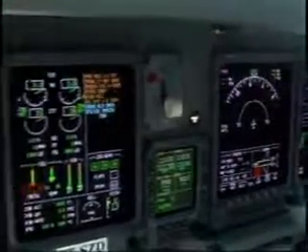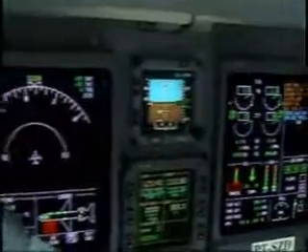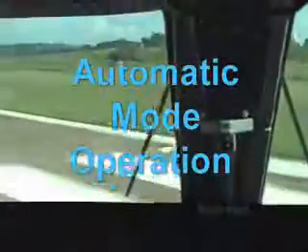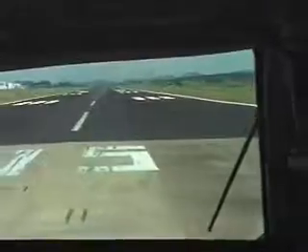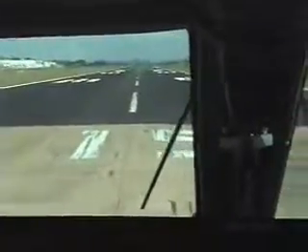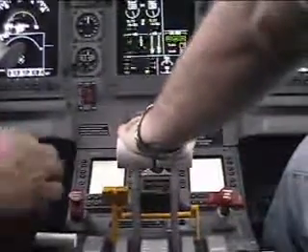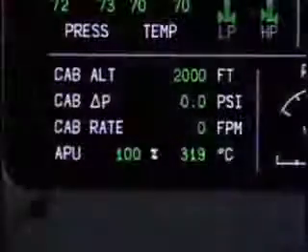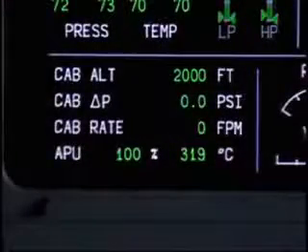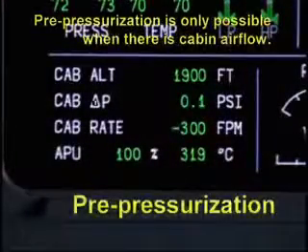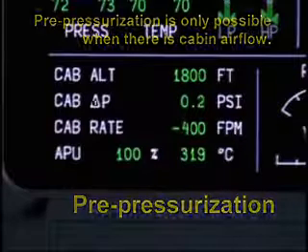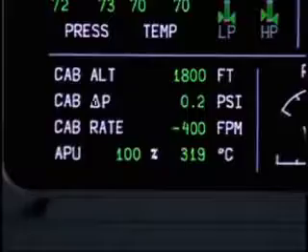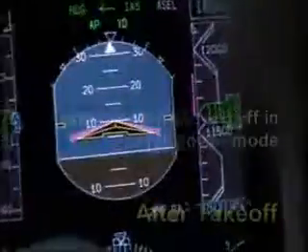Check the corresponding ICAS indications for a typical flight departing from a 2,100 feet pressure altitude airport and cruising at 26,000 feet. The digital controller does all the work, despite the different operational conditions. Observe the pre-pressurization that takes place after full throttle is applied. During the pre-pressurization phase, you may detect an irregular cabin altitude variation, but this is normal.